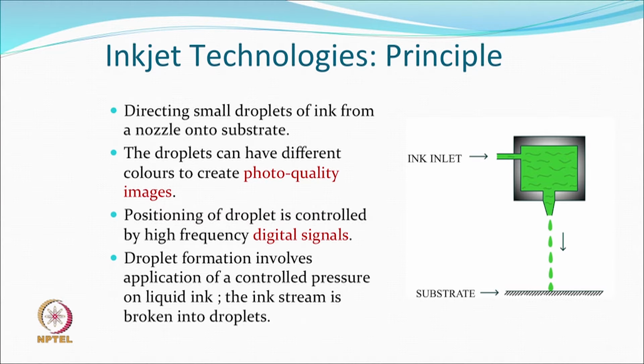So, all that information has to be sent through various transducers to the jetting area and the nozzle, and then there has to be a mechanism of continuous feeding, breaking the jet into droplets, and then we hope that there is an affinity to the substrate and there is a process post printing which can ensure that there is a fixation of whatever drops that have come. So, one thing which is very clear is we are looking at drops.